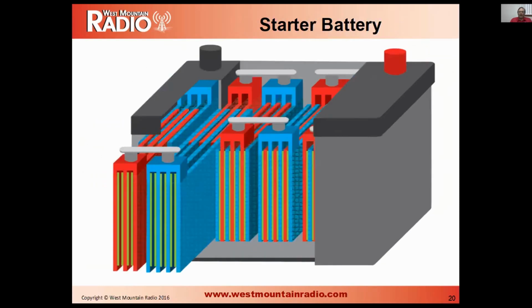The starter battery is the kind of battery that you have for your vehicles. The big difference on the starter batteries, and you can get them in both the gel and the flooded, is that in order to get a lot of cold cranking amps out of that battery, they've added a lot of surface area to the plates. They used to just drill holes in the plates. Now they use kind of a steel roll paste that they put over the plates. The more surface area, the more instantaneous energy you get out. It doesn't actually increase the total energy in the battery, just the instantaneous energy.